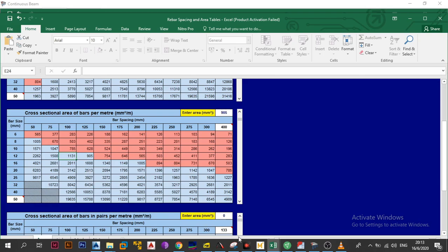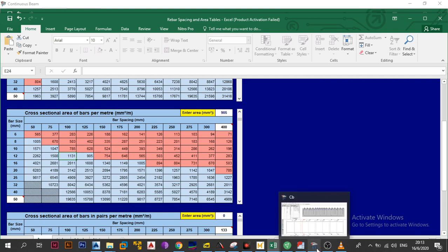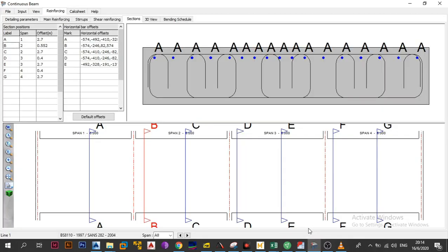All you need to do next is check for the punching shear within the slab and see if it's going to be okay, which is what we will need to do next. But now, what I've just done is you've confirmed 7 Y12s at 125. This is how it works. So this is how you would do it. This is how you actually design. So in this case, this is what we've done. We have actually designed the column strip for that.